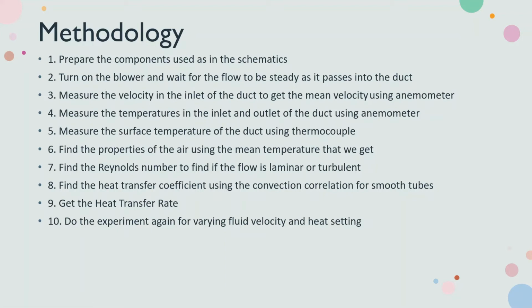And then we use the anemometer to measure the velocity in the inlet of the duct and to get the mean velocity, and also measure the inlet and outlet mean temperatures. And then we use the thermocouple to find the surface temperature, and then we find the properties of the air using the mean temperature that we get.